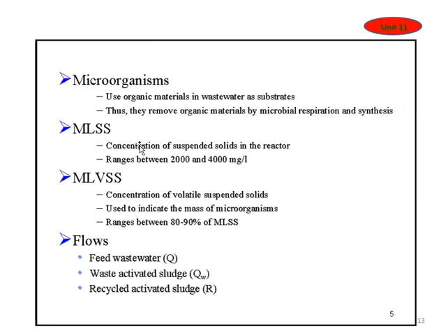Mixed liquor suspended solids, what is this one? This is the amount of bacteria and waste material per unit volume of the wastewater, called the MLSS. So you can see that generally in the aeration tank, the quantity of this mixture is 2000 to 4000 milligrams per liter. So this is mixed liquor suspended solids. There is another type, mixed liquor volatile suspended solids, also there, and generally it is 80 to 90% of the MLSS. So most of the solid mass in the wastewater is the MLVSS.